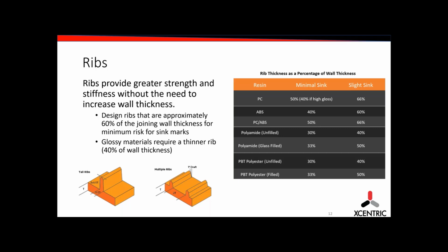And again, when we're talking about a nominal wall that's quite thin with respect to some designs, when you add a rib pack on the back, we start getting the strength that you need from your part. There are some things to consider when you're adding a rib. We'd like to keep the ribs about 60% of the nominal wall thickness. Right there where John has the cursor.